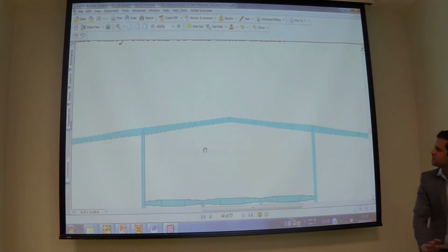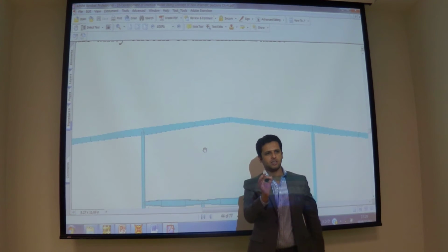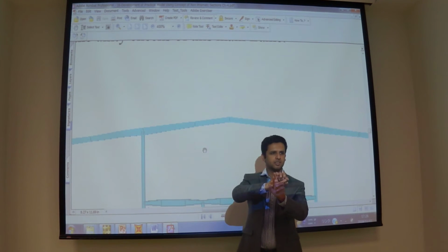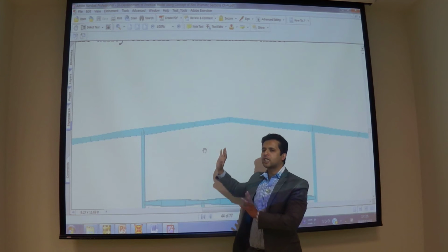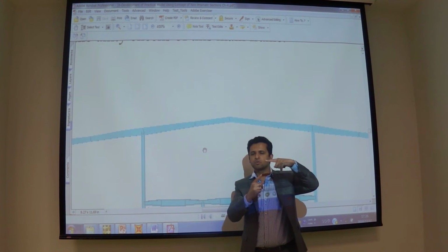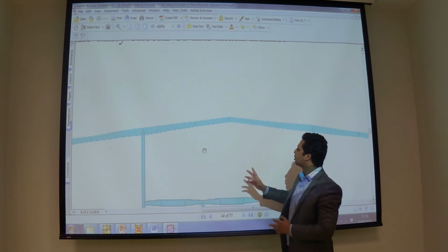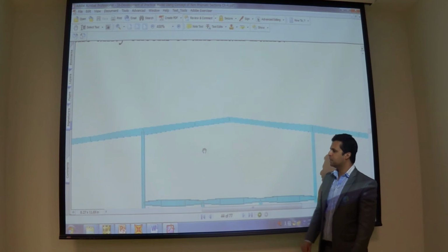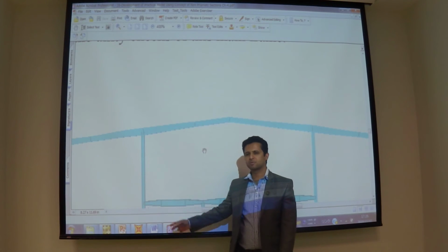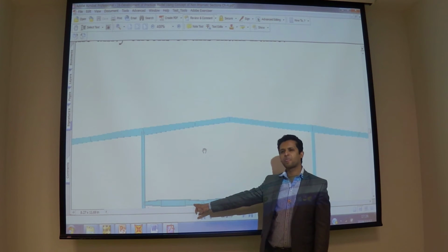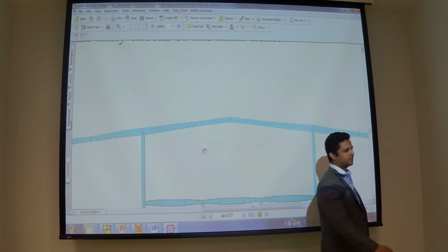Yes. Sometimes, for example, I have reduced the depth so much that there are two things to check: one is strength and one is deflection. So you have to check both. Sometimes the unity check is 0.6, but deflection is high. So in order to control deflection, you have to keep up. This is how I provide beams. I do not provide a straight beam. I taper the beams. You understand? Why? Because there is very little bending moment at the sides.